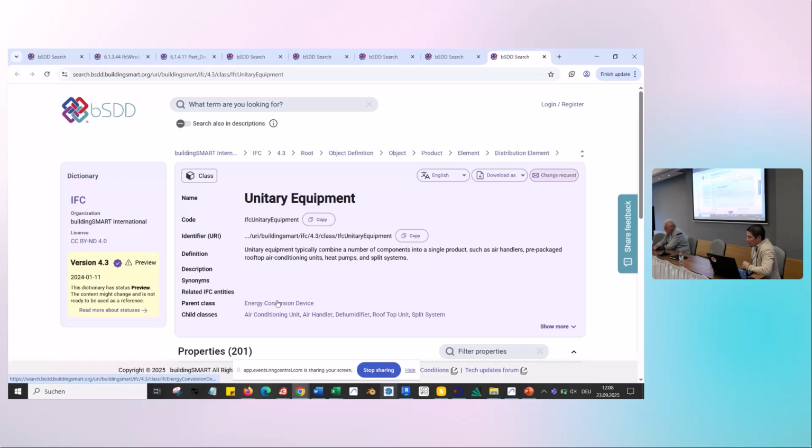I mean, as you now have the bSDD, which can contain so many other classification systems, but you still insist on focusing on what's now strictly defined within IFC 4.3, and you always will bump into certain limitations. Yeah, of course. I was under the impression that gradually we would say IFC does not have to be that broad and big, because it's effectively becoming a blocking issue.